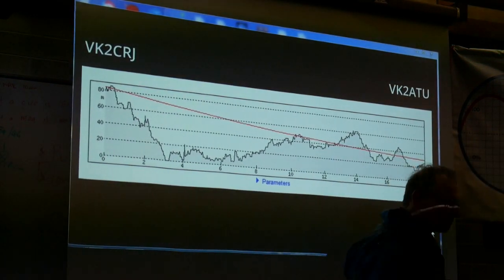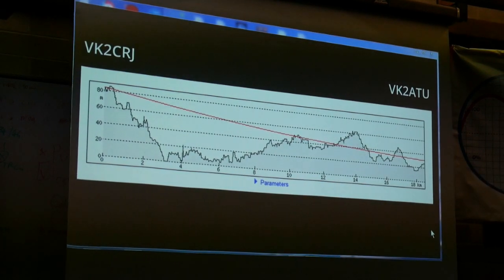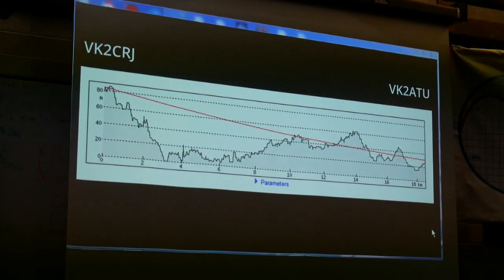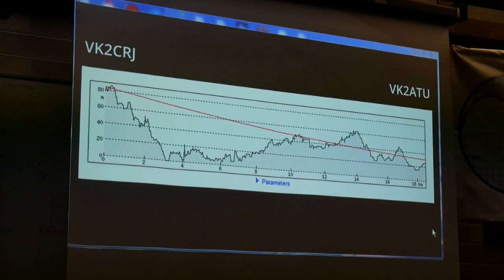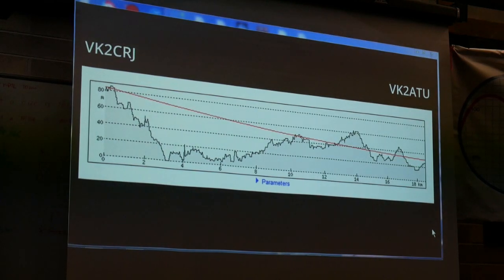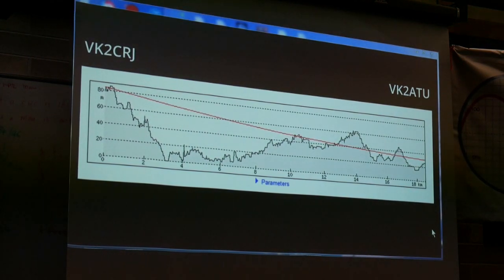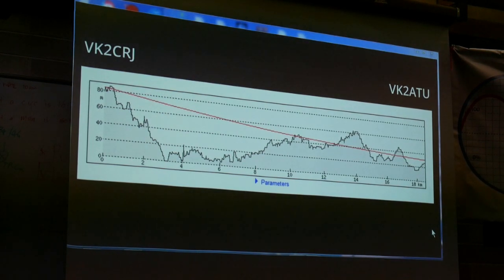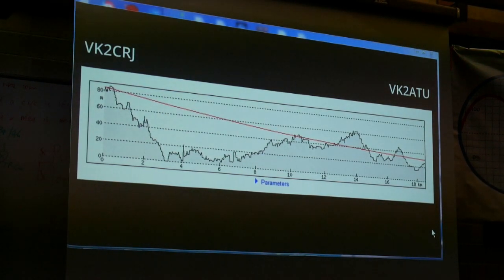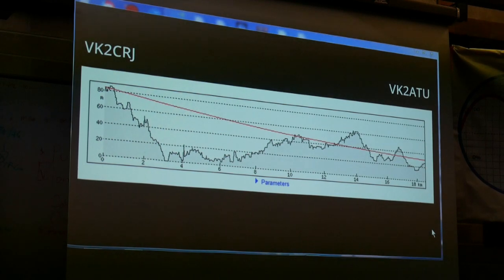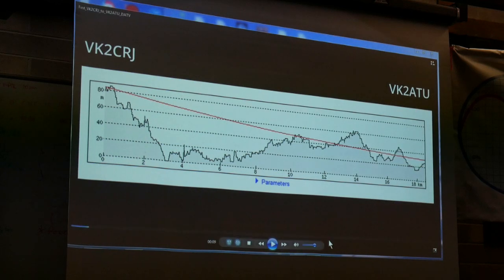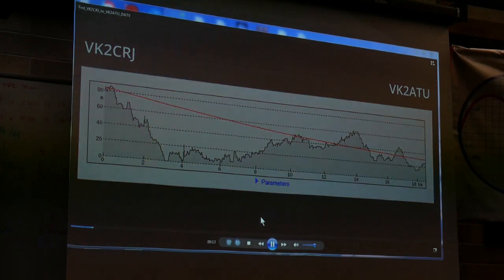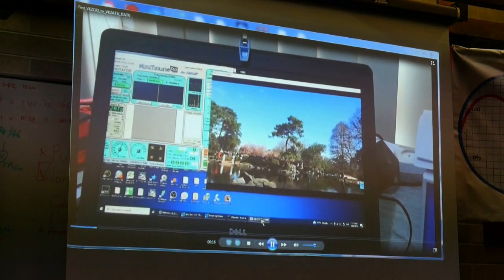How wide are the hills? The point is you've got to have some 12.5 centimetre features to resonate with the waves. And if they resonate with the signal, they're going to retransmit it in a different direction. The only 12.5 centimetre things are magpies and kookaburras sitting on a tree. On 70 centimetres it's impossible to fox hunt in a pine forest because all the pine needles absorb the signal. They're all the right length and they're resistive, so they absorb the signal. Six metres is impossible because the trees are 6 metres apart.